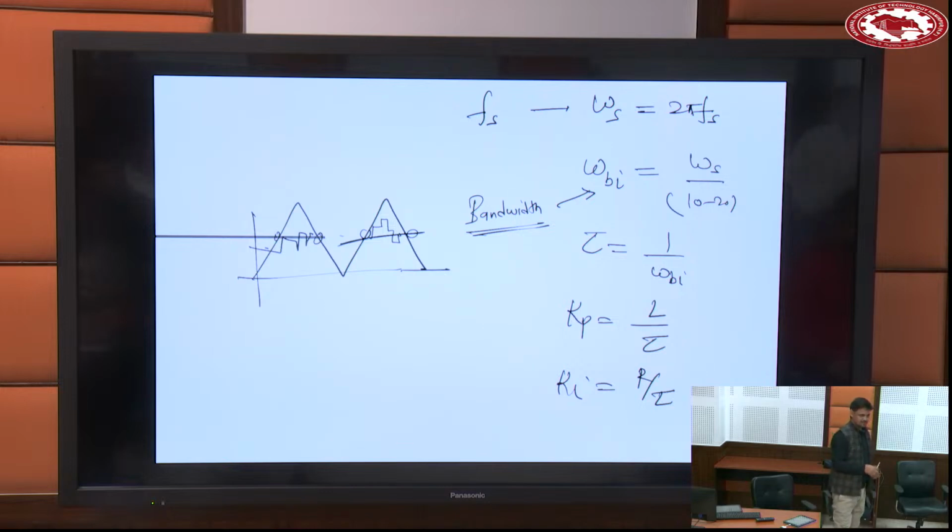Otherwise, if you reduce the frequency, the same synchronous machine will start rotating. You will not need any additional damper winding or anything. That is a special type of starting method. Because now you have made it compatible, it is within its limits, so it can follow. This is how. So keep in mind, Professor Karimi will come to this; he said in the last lecture that he will come to that level.